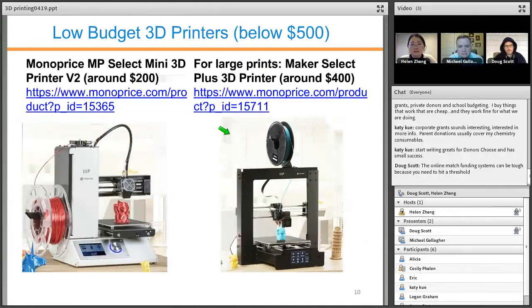They are rated for both, but as the instructor in the room, I've chosen to use PLA, because the PLA doesn't give off the gases that the ABS will. The PLA is a starch base, so it's like a corn or a sugar starch based material with the polylactic acid. And the printers here, you'll see they don't have any enclosures or exhaust systems. So when I used to print in ABS, you'd fill the room with a stink of plastic, which I didn't think was healthy for anyone. So I chose to go with the PLA.